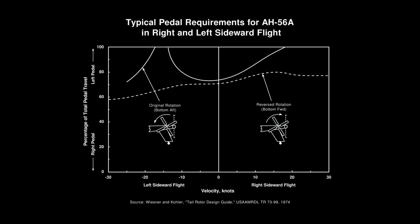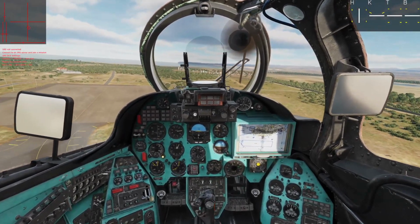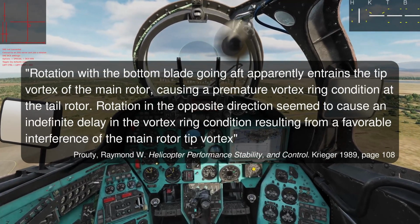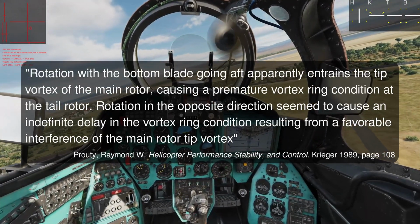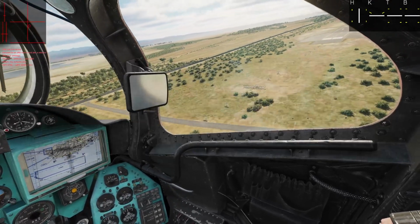The Huey actually doesn't do that, but the Mi-24 does, and most more modern helicopters use that orientation because it's beneficial. The reason isn't quite well understood, but it has to do with some beneficial interaction between the main rotor wake and the tail rotor, and it helps to prevent tail rotor VRS. And I don't think it should be entering it quite that easily.